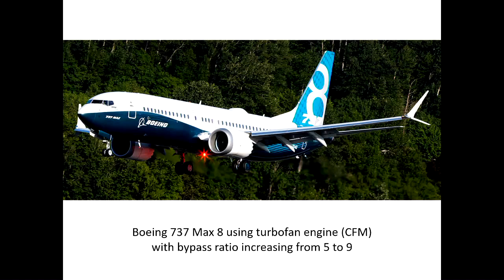why do I still need the fan, right? A fan with the engine cover still limits the amount of air or amount of bypass ratio that I can have. Why not I just get rid of the engine cover, just use a propeller in front of the engine, so that I'm just propelling open air. The bypass ratio can be infinity, right? So that's the other design called turboprop.